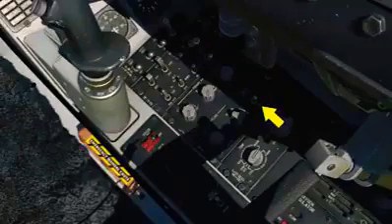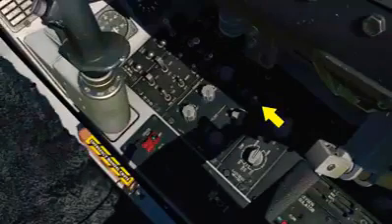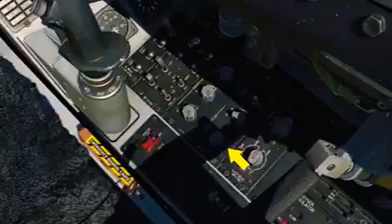The malfunction indicator light switch sets the AOA indexer, nose wheel steering, and air refueling lights, the DED, ECM control panel, MFDs, and PFLD, as well as the threat warning systems, to either dim or bright. The flood instrument knob controls floodlight intensity on the instrument panel, and the flood console knob controls floodlight intensity on the left and right consoles.